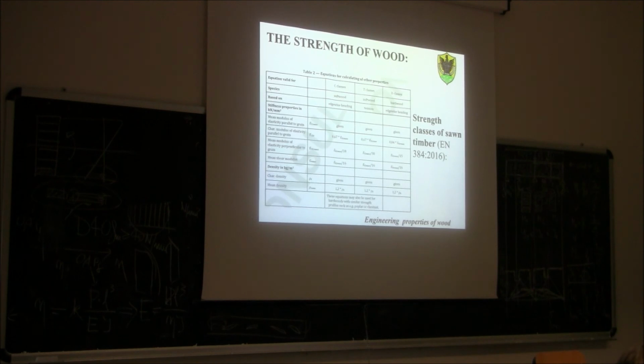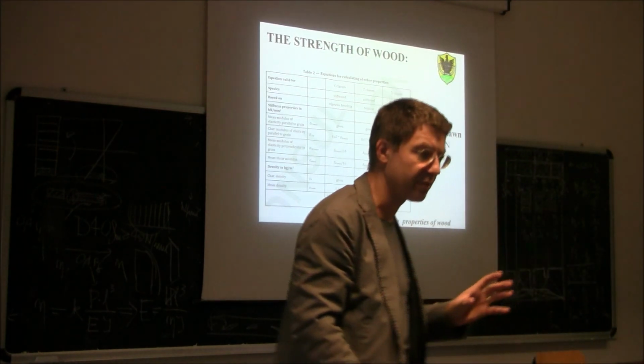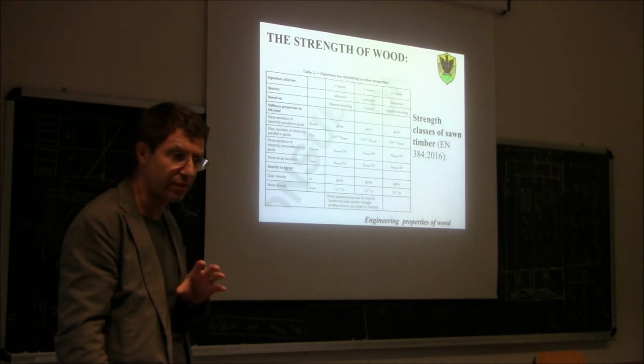It could be between -1, which doesn't make physical sense, and 0.5. So if we do G equal to E divided by 2 times (1 plus 0.5), that is 2 times 1.5, which is 3. So for an elastic, homogeneous and isotropic material, the shear modulus is 1/3 of the modular elasticity.